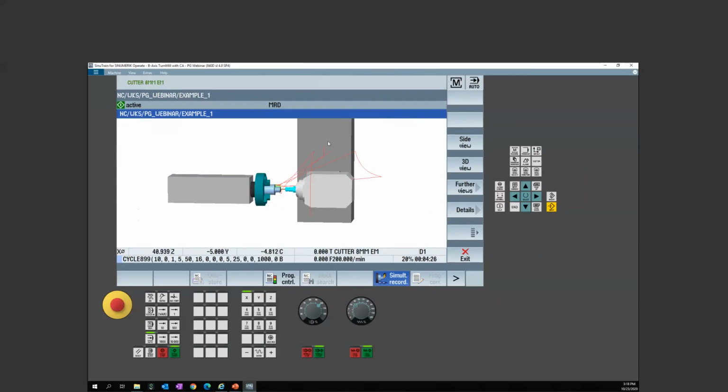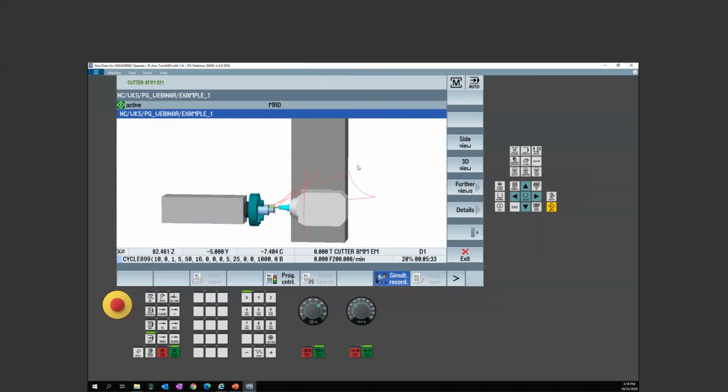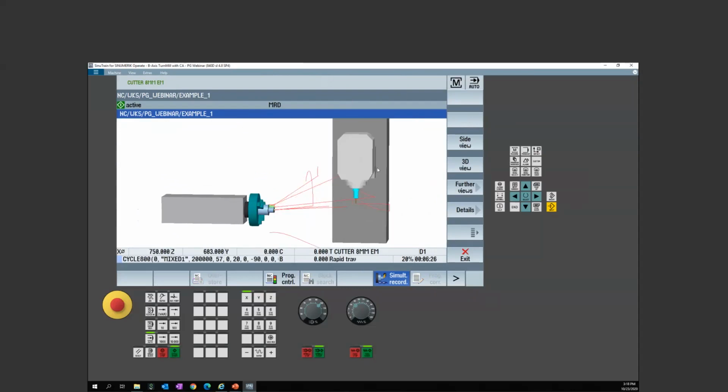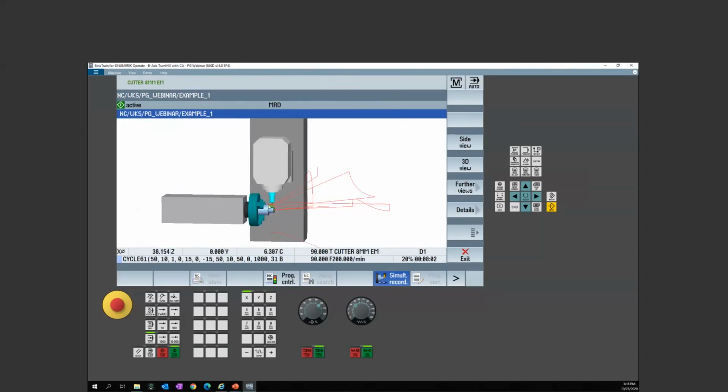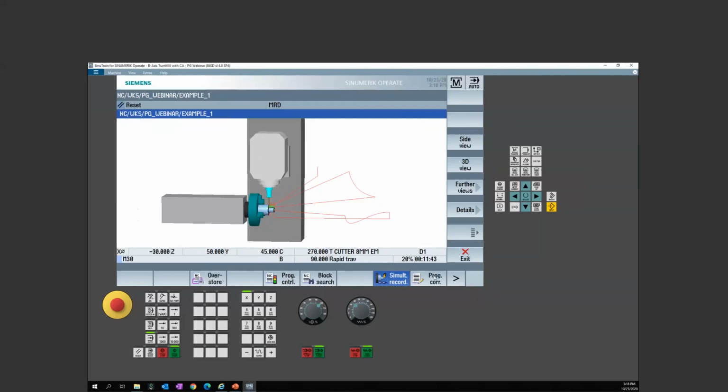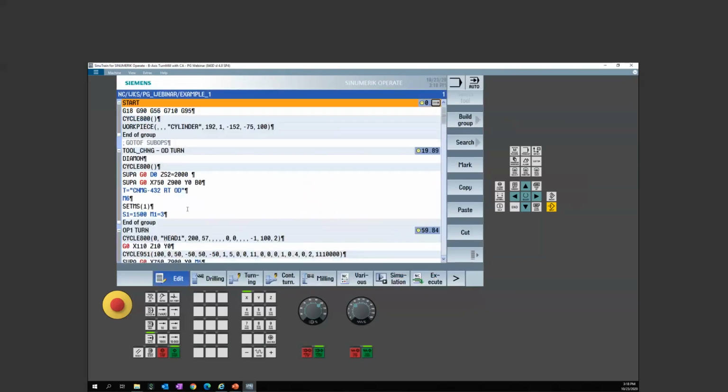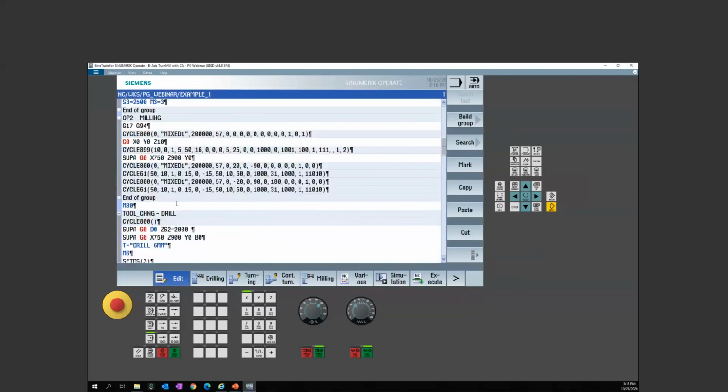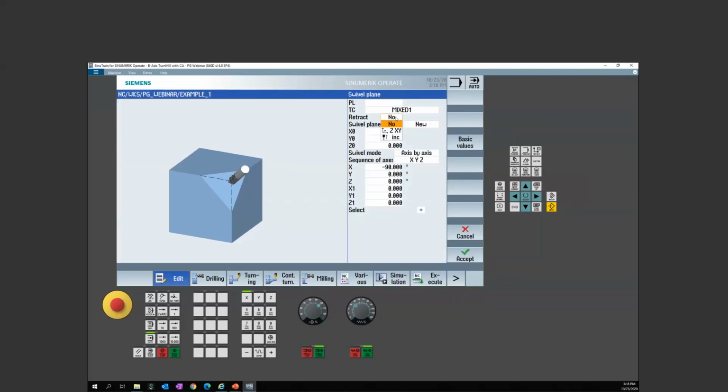So she's not going very high on the slide, you see, because in this case, my SUPA, so I am like right on that edge. I could have been below center line when I approached that. So you want to be careful there. If I use a retract strategy inside the cycle, then I can have the machine drive to a predefined location. So there's multiple strategy scenarios. You are going to be dependent on how the OEM commissioned the machine.